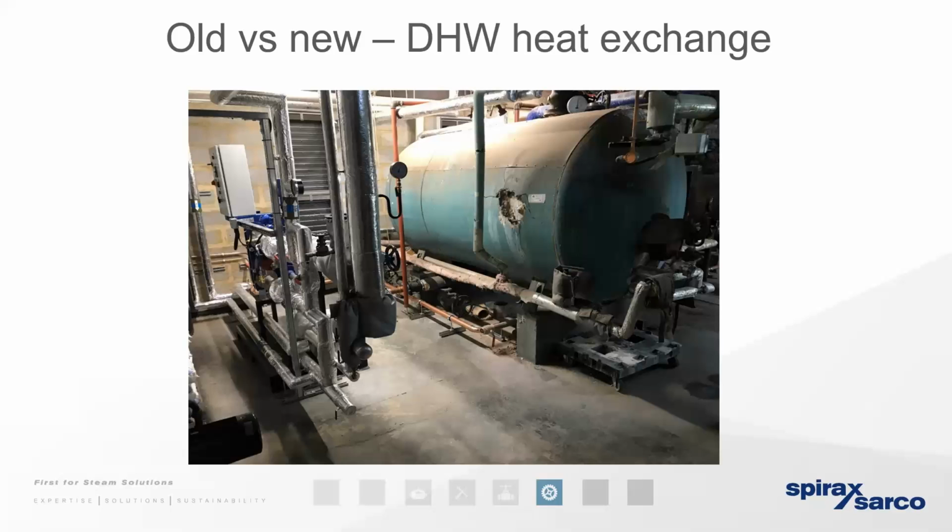And remember, if we're using a tube bundle assembly rather than plates, then we're going to get an inefficient A value. And that inefficient A value, as a result of the small heat transfer surface area with the storage solution, means we've got to compensate for that. We do that by condensing the steam at a higher pressure.